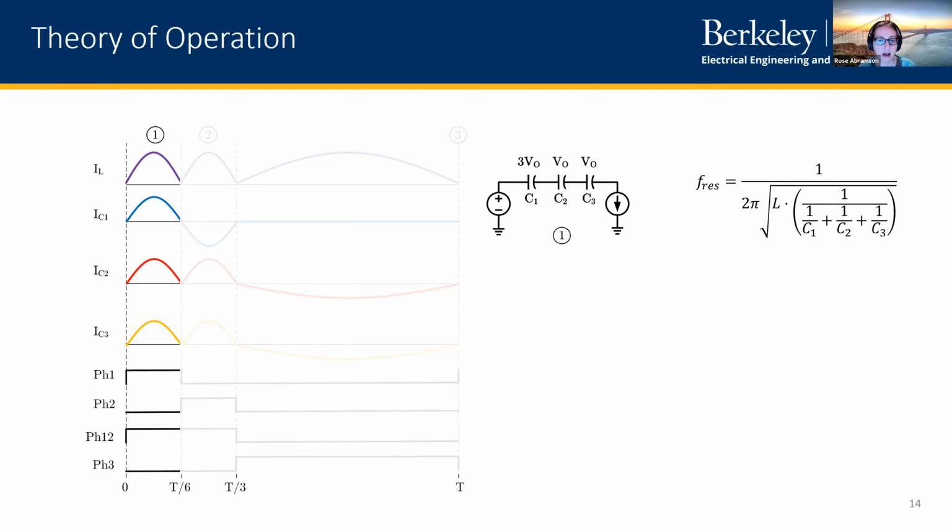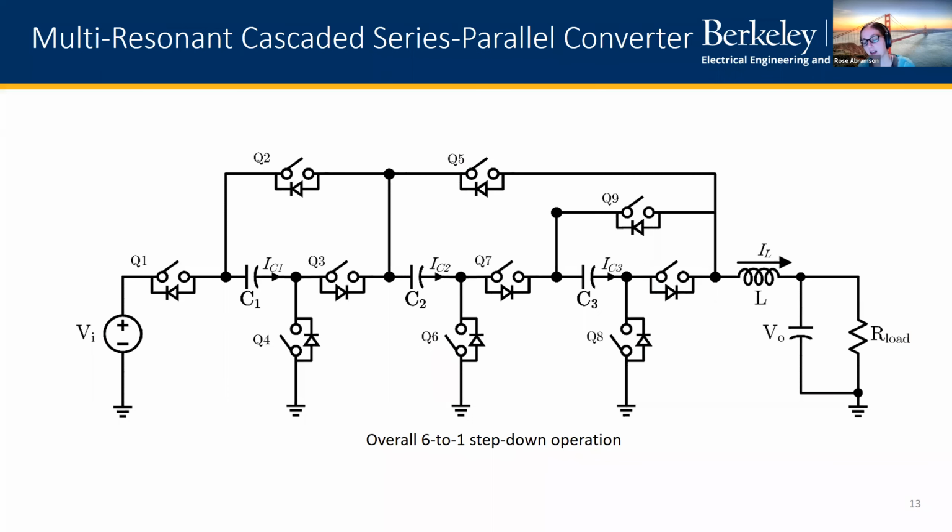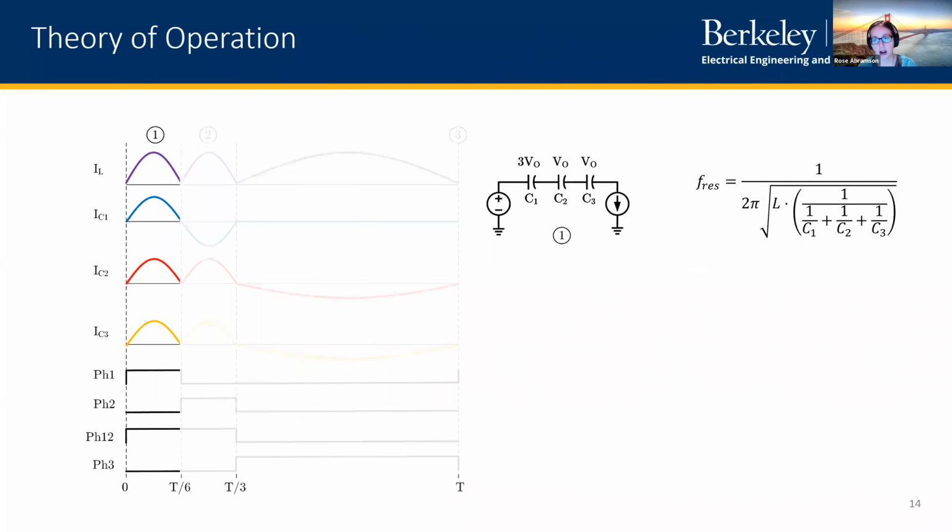And here, if you look back at this circuit topology, you can see that the output of the switch capacitor converter has an inductor. And this inductor allows us to operate with soft charging, where we reduce the spikiness of the capacitor charge and discharge current. And we can essentially charge and discharge them with an almost constant current. And that reduces a lot of the charge distribution loss in switching these capacitors. So here I'm just modeling the current through the inductor as effectively a current source.